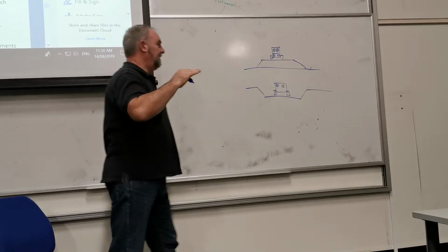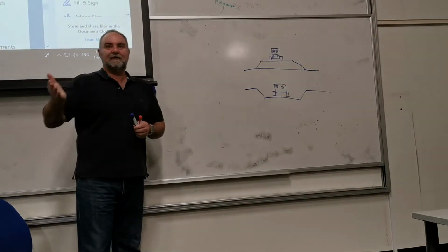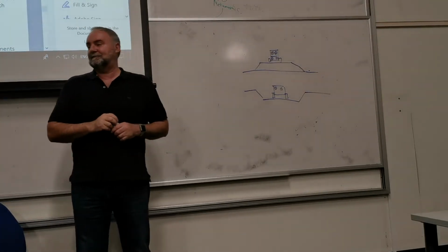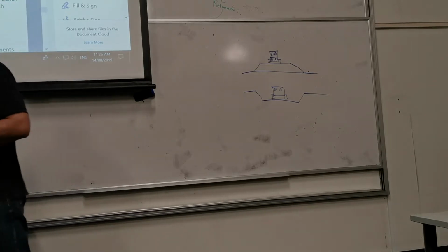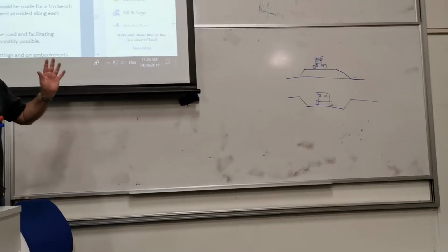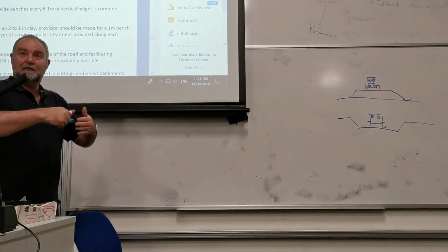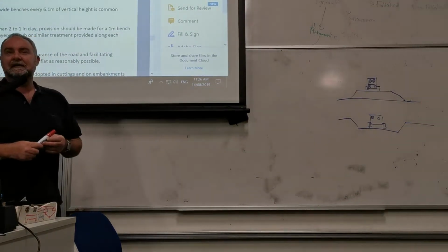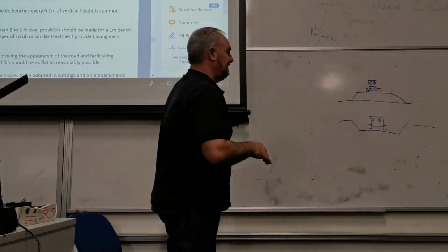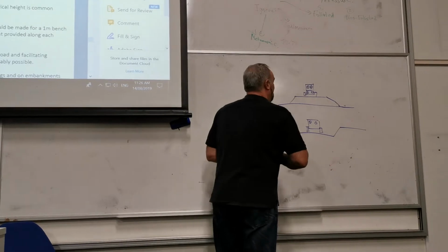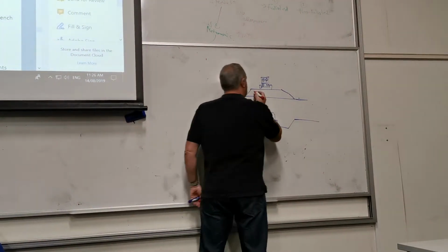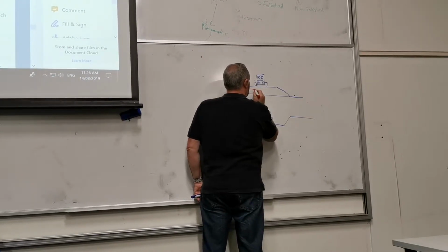Along the road, our job was normally from the start of the new piece of road to the end to balance the quantities. So we would go along the road, that was the new road that we did, and work out the quantities, and we might have, say, too much cut. By the way, these are questions also in the test. So one way of balancing it so we had less cut, an obvious way, was to drop down the road here like this.